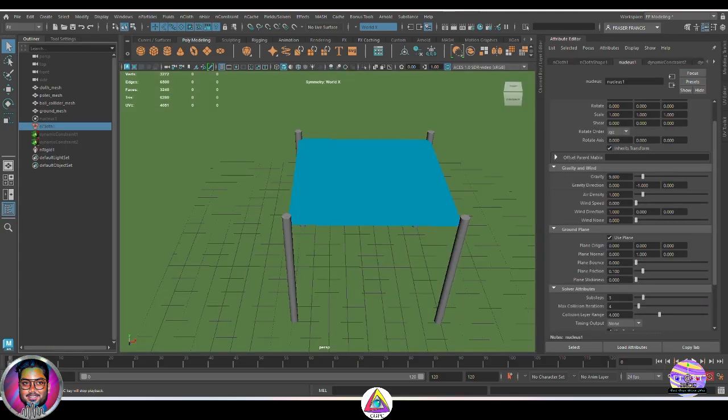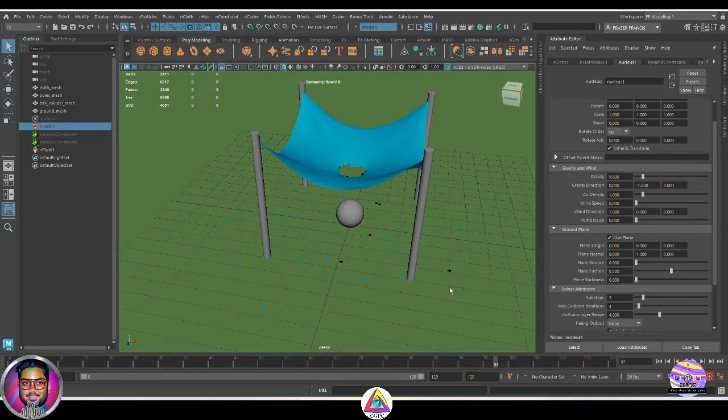Okay. So now currently, as you can see, with what we have over here, the particles are sliding off, right? So if we increase this friction, let's try 0.5 and let's run this once more. So it's not going to slide off like that. It's going to remain closer to the impact area. Okay. We can increase it even further. Let's make it 1 and see. Okay. So this looks more natural.